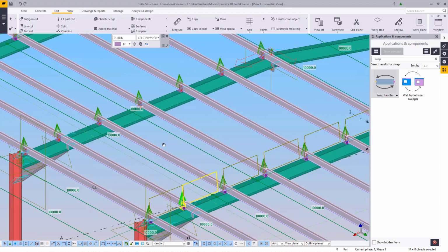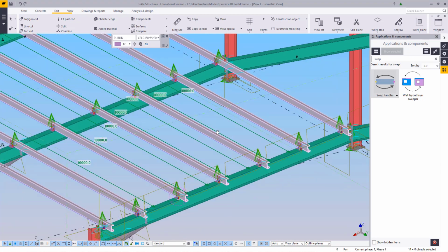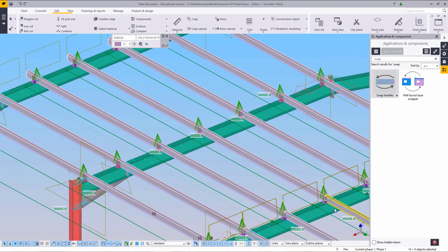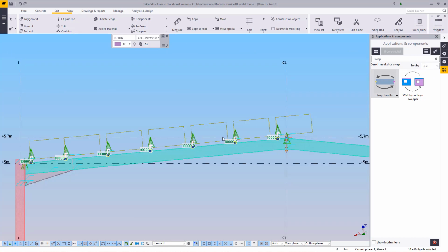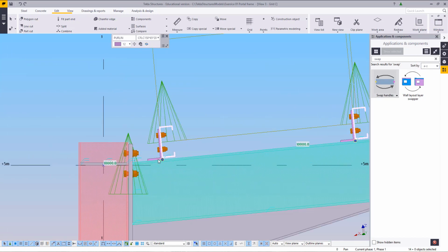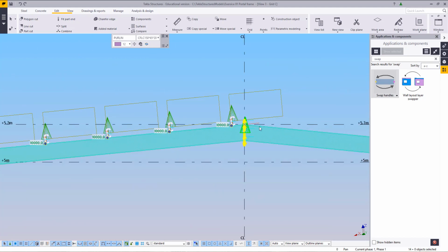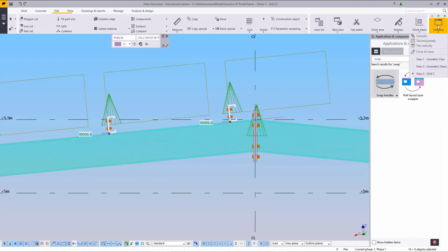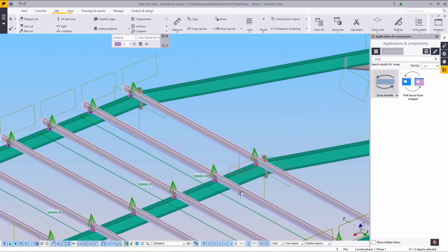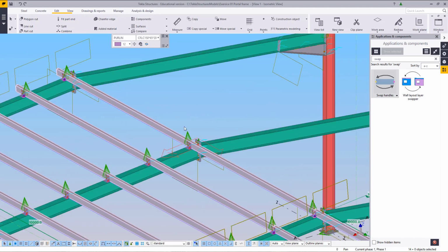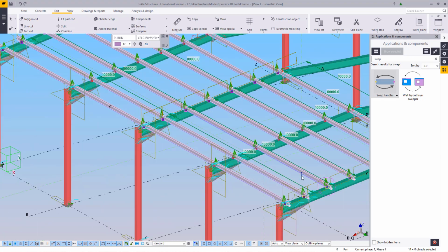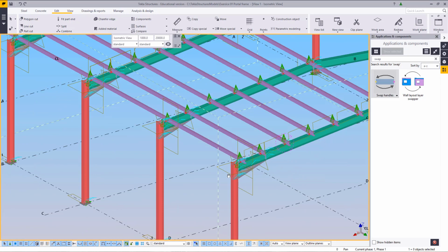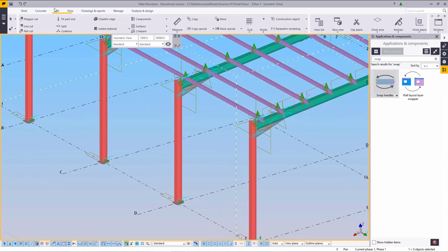Once you've done that, just go through and make sure that all your connections are still fine. There's nothing that I can see that obviously broke, as sometimes things will break. The other thing that you have to be careful about is that swap handles only works on your axes. As we are currently using a flat area on top of the rafter, it is not a problem, but if we have switched back to the global ones, then our swap handles won't work as well.